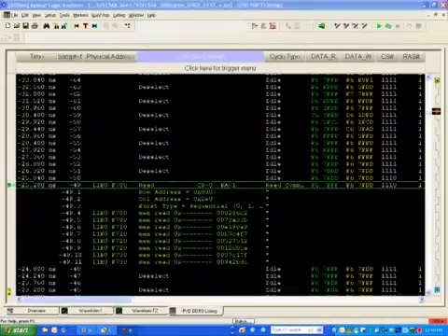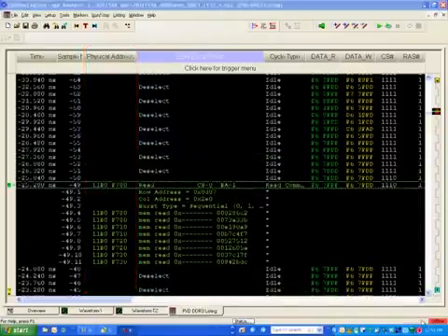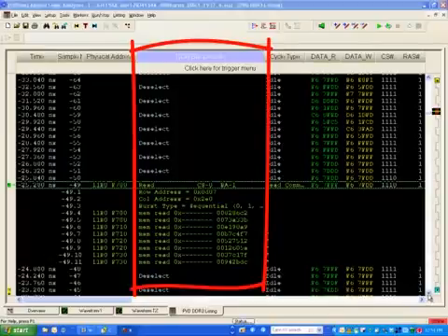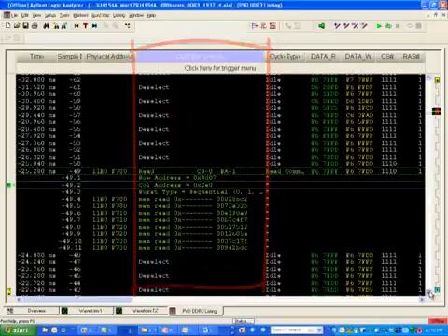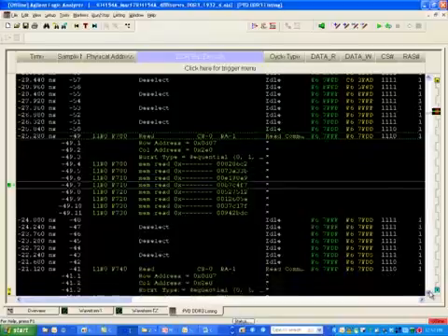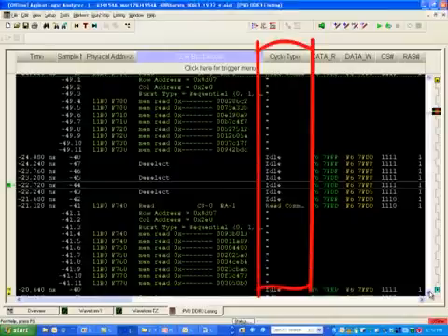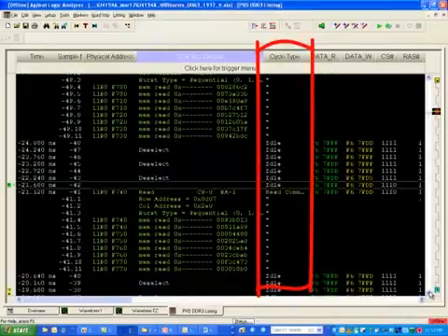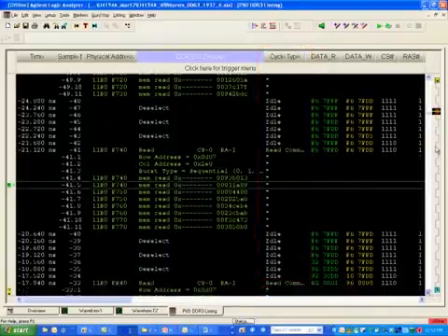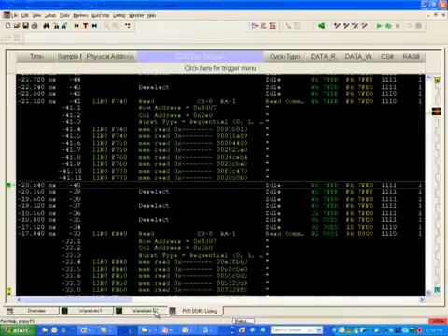In the listing window, we have 3 extra labels created by the decoder: the physical address and the actual DDR bus decode, where the valid read command information includes the row address from the activate, the column address from that actual read or write command, and then the data associated with the command. There's also a cycle type that lets us know what type of command is being executed on that particular sample. We can scroll through the entire listing and see our particular back-to-back burst that was captured, and all other data for up to 200 meg deep around the trigger point.